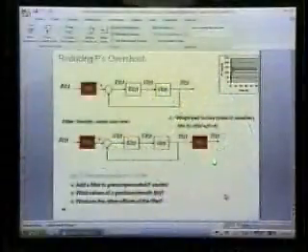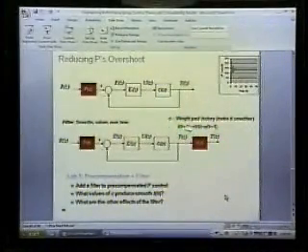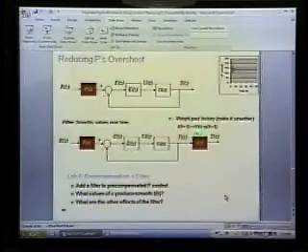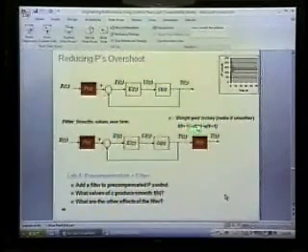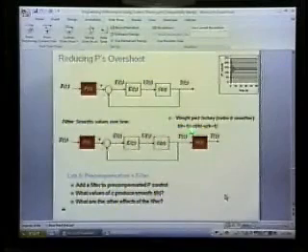The way I might smooth this is I say that my final output, T, you can subtract one from these time constants if that throws you, could be T of K equals C times T of K minus 1 plus Y of K. But the idea is I'm going to smooth it. I'm just going to take part of my previous T and use that as a smoothing for what I'm getting for the actual Y. So if the C here is 0, then I get exactly the Y value. And as C gets larger, I'm taking more and more of the T and less of the Y. Does that make intuitive sense at least?